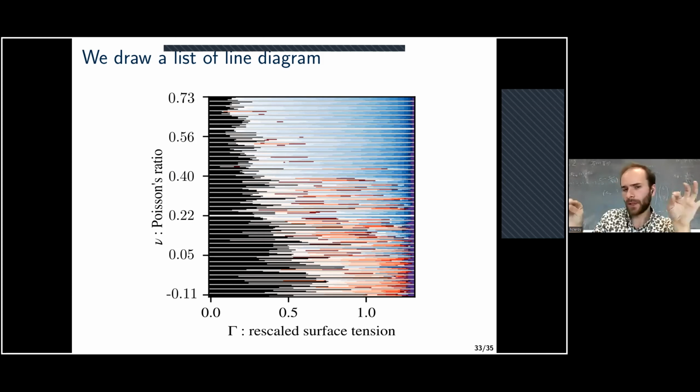So each particle is a single line, and then I sort each of these particles by the Poisson ratio. And as you can see, this definition of the Poisson ratio that we built previously helps to understand whether the particle will have this tendency of creating a fiber or a disk. Here again, there seem to be more fibers than bulks overall, and I think that might be a general feature, that fibers offer more freedom. But still, the main point is that a high Poisson ratio still favors the formation of fibers.